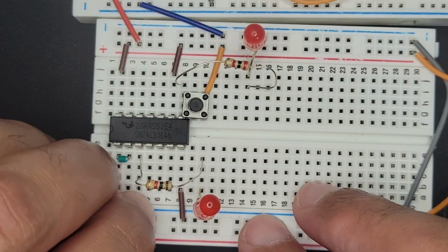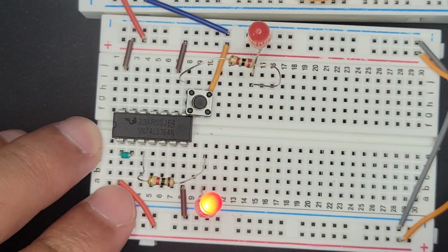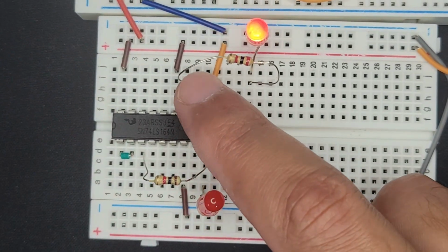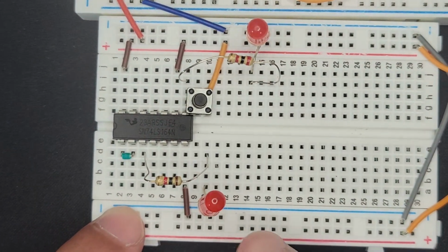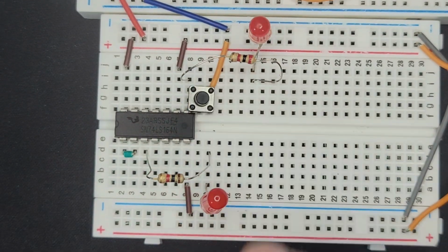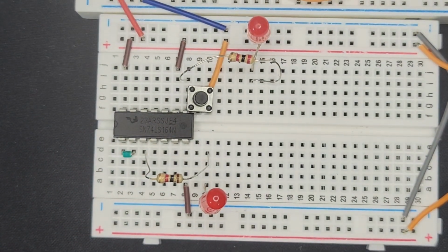Okay, so that's off. So if we give the input a 1 again, then it gets it on, and now it doesn't. So it's a little finicky, and I'm assuming it's because, like, look at that, it's weird. Well, this is a floating input right now. That's another thing. I need to pull down the inputs.